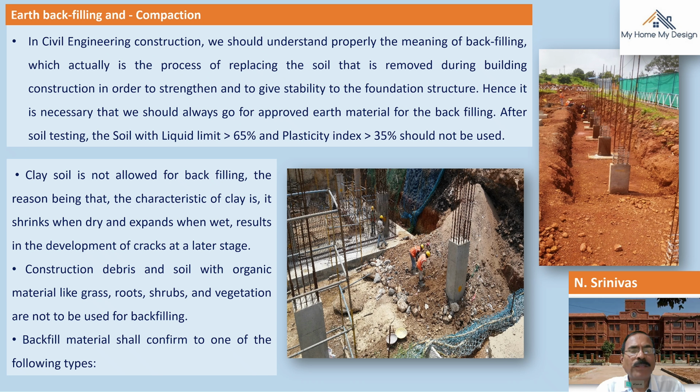Now, what is earth backfilling and compaction? In civil engineering construction, we should understand properly the meaning of backfilling, which is the process of replacing the soil that is removed during building construction in order to strengthen and give stability to the foundation structure. Hence, it is necessary that we always go for approved earth material for the backfilling. After soil testing, soil with a liquid limit greater than 65% and plasticity index greater than 35% should not be used. See here, point to be noted.